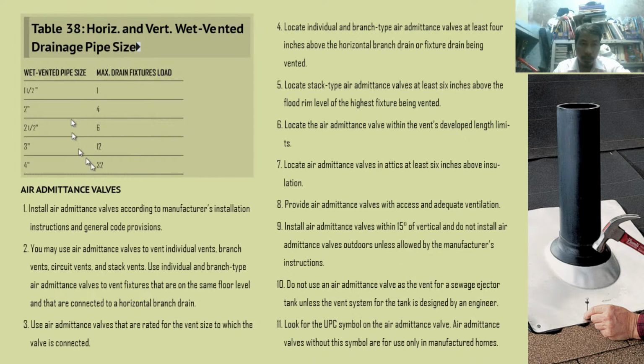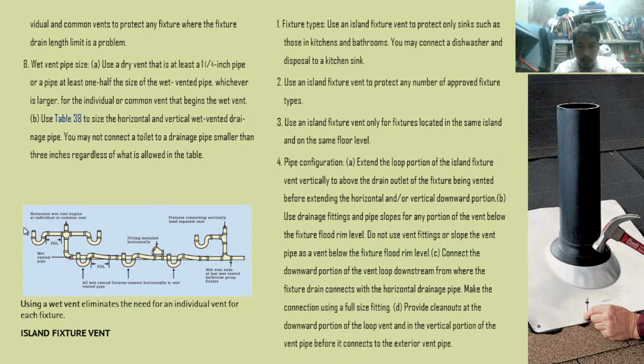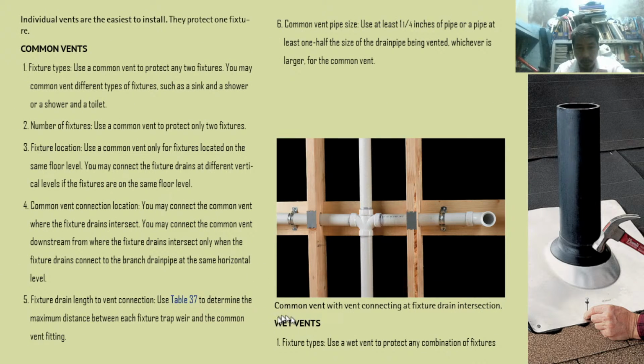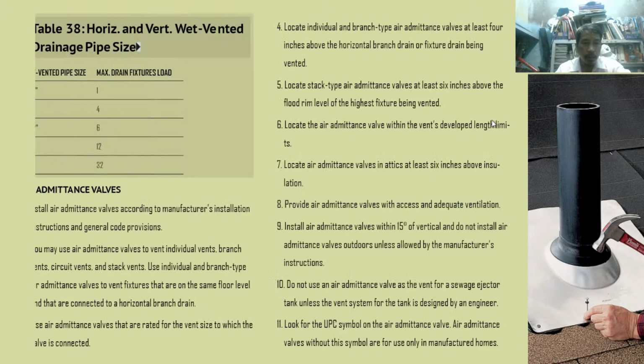These are the fixture loads. So that is for table 38. That is for wet vents, so for wet vents, we can use table 38.